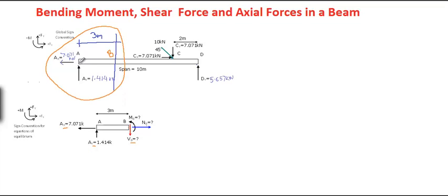So in this case, free body diagram AB is easier, because on the right hand side you have support reaction, the vertical external load at C, and the horizontal external load at C. But on the left hand side, only the reactions are the load. So the left hand side is easier in this case.